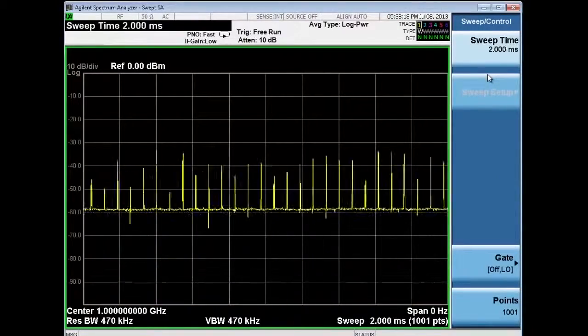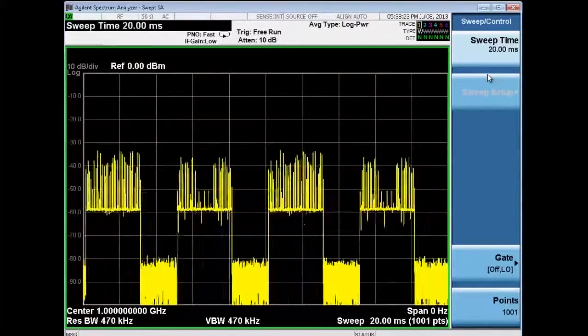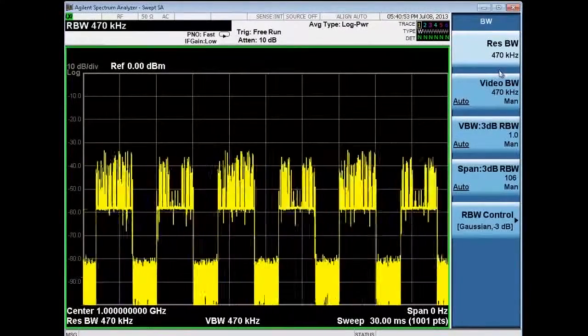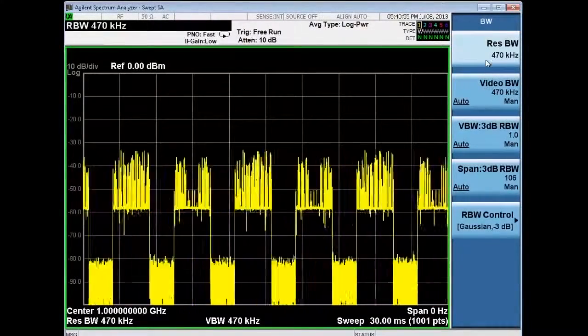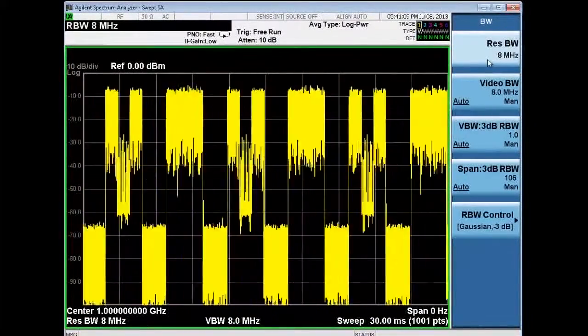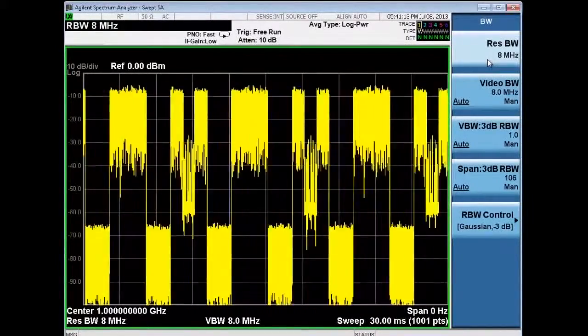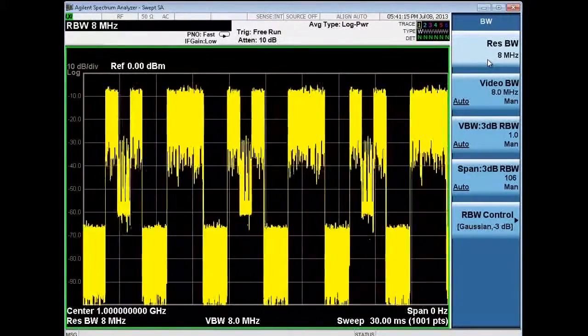If you are measuring waveforms with short rise times or fairly narrow pulse widths, your bandwidth will be limited by your analyzer's resolution bandwidth filter. In most cases, this is less than 10 megahertz. While these displays are useful, they are missing a large amount of spectral content, which can make it very difficult to detect and troubleshoot problems.